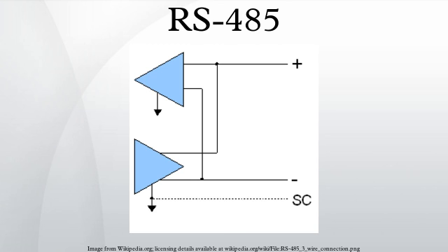The master device itself would provide termination if it were located at a physical end of the wires, but that is often a bad design, as the master would be better located at a halfway point between the slave devices, to maximize signal strength and therefore line distance and speed. Applying the bias at multiple node locations could possibly cause a violation of the RS-485 specification and cause communications to malfunction. Three-wire connection: connection of a third wire between the source and receiver may be done to limit the common mode voltage that can be impressed on the receiver inputs.